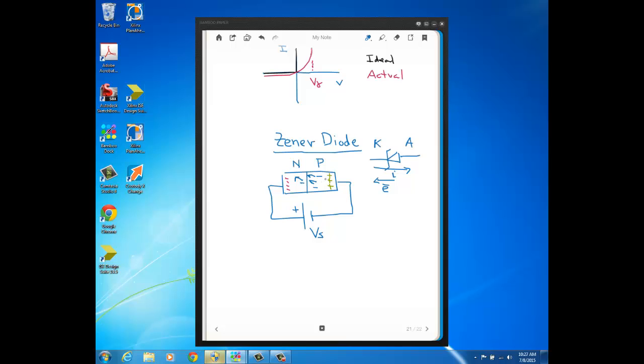Okay, a normal diode, a diode that's not a Zener diode, would become defective once this avalanche current would start to flow. It would essentially burn up, and your junction would be no good and your diode would be defective. Okay, but with the Zener diode under this condition, we do have a current flowing cathode to anode, and that's a reverse bias current. Now, ideally, when this current starts to flow, it starts to flow instantaneously. Okay, so ideally we would show this instantaneous current as just a vertical line straight down, and the reverse bias voltage at which this occurs is the Zener voltage VZ.